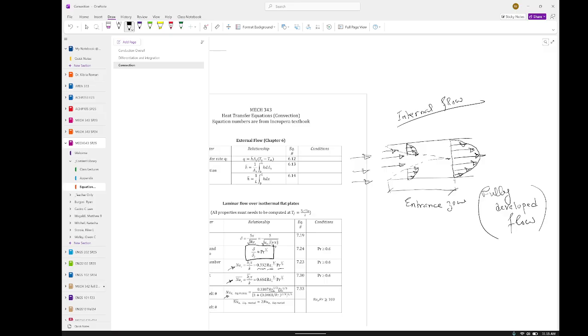Bottom one, when it is touching my hand, it is going to try to move and my hand is going to resist it to its maximum, right? The top layers have less resistance, right? But because of the bottom resistance, it is going to propagate to the top layers, as if those layers are fluid or air that is flowing. You understand? So that's the boundary layer. Anyway, any questions so far?